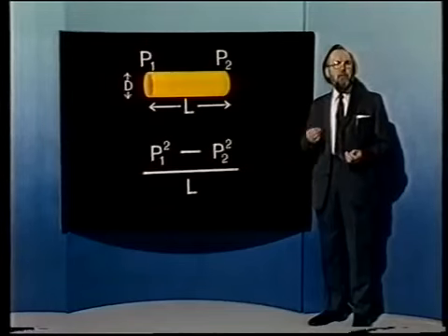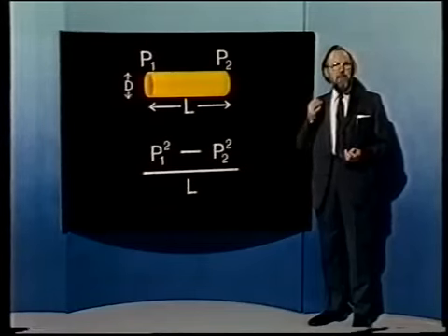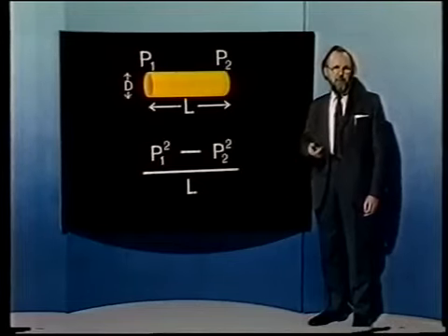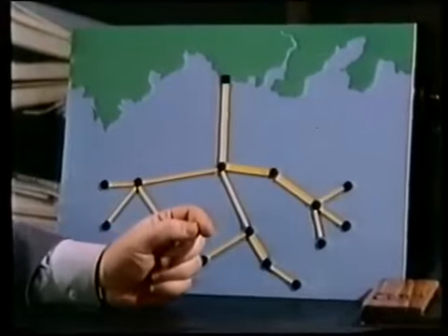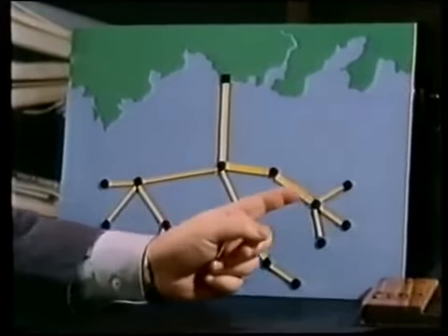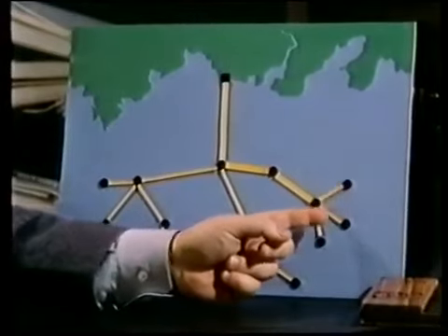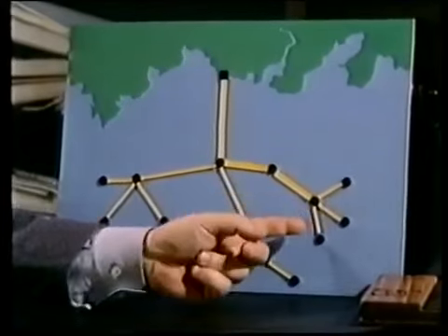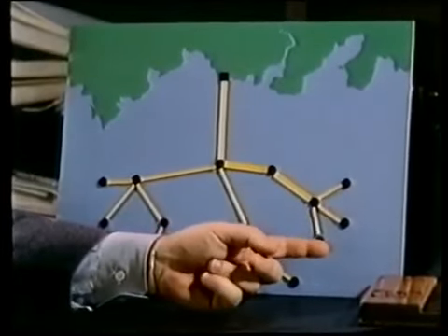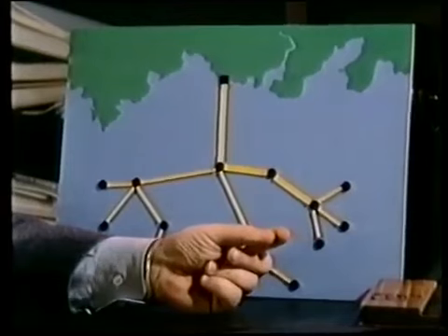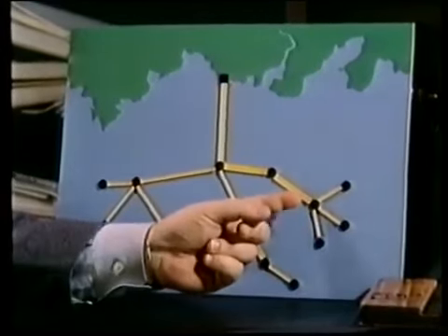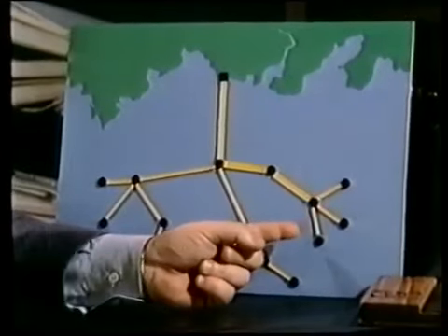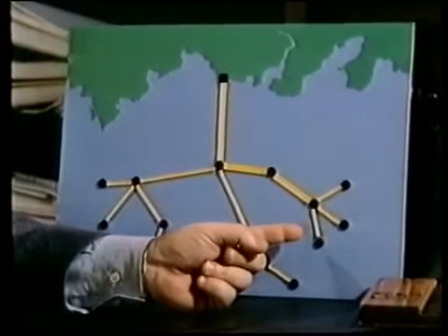Now, the trick which Dr. Frank found was to develop ways of simplifying the problem by discarding all but a few combinations of pipe diameters. The process that we developed essentially started at the pendant node part and collapsed these 3 branches into a single equivalent branch with a set of possible diameter combinations and a set of associated costs, which were the only ones that could possibly be in the optimal assignment.